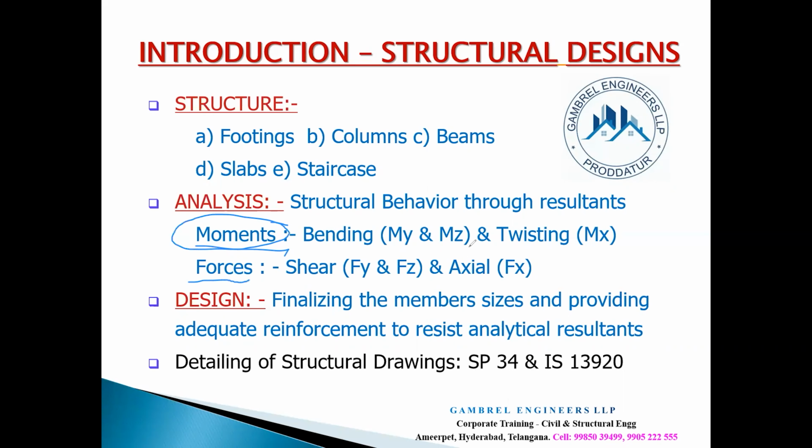Moments usually would be in the form of bending moments in 2 directions and a twisting moment in 1 direction, and forces are shear forces in 2 directions and an axial force in 1 direction. Very simple. So we know what a structure is, and we also know what analysis is. Analysis is understanding structural behavior through resultants, which are moments and forces. Moments are classified into 2: bending moment and twisting moment. Forces are classified into 2: shear force and axial force.